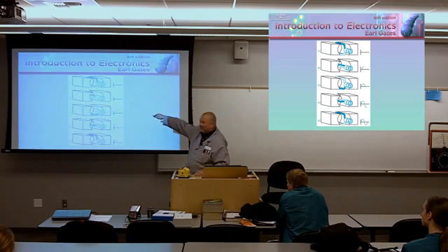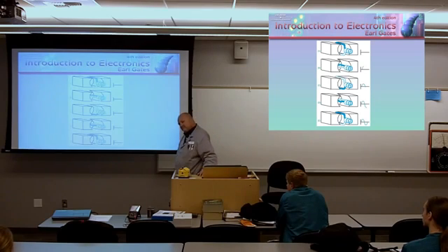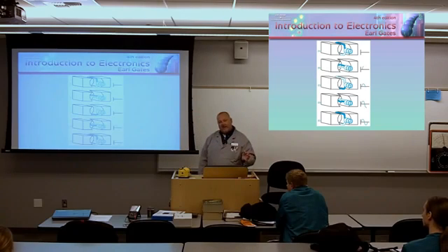When we rotate that armature now, we're going to connect the shaft to this, and we're going to blow on it and make the shaft turn through a wind turbine, or we're going to use steam and rotate the shaft through a steam turbine or whatever. But when we rotate the shaft now, how many degrees have I rotated it from my peak? 90. So right now, is the armature parallel or perpendicular? Perpendicular. What does Faraday's law say? When I'm perpendicular to the lines of flux, I generate my maximum amount of current.